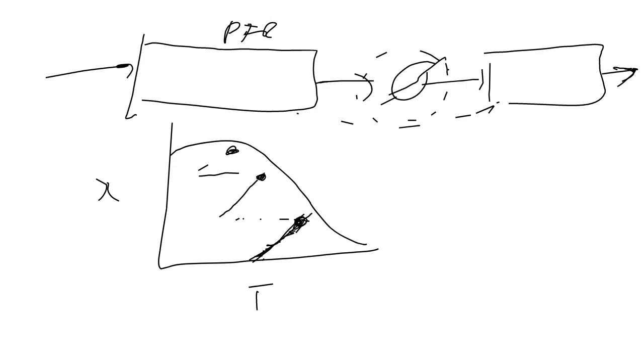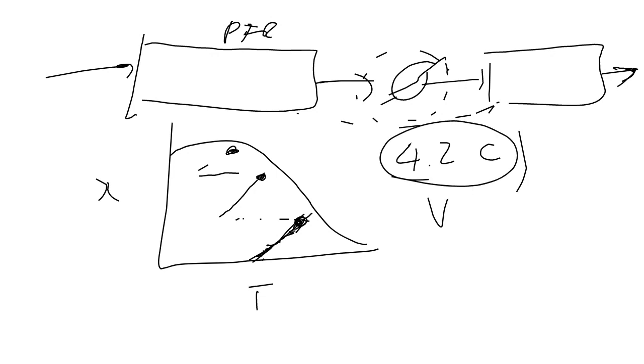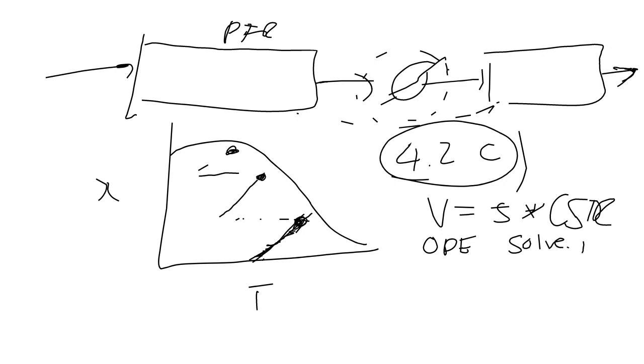So when you model this, I would actually challenge you to model that 4.2C. For that 4.2C, make your reactor volume really large. Take a volume like 5 times your biggest CSTR volume that you calculated. This is good practice, so practice this for, almost I want to say, your exam. And then we are going to have our normal solve IVP or ODE, or solve IVP if you want to use events.